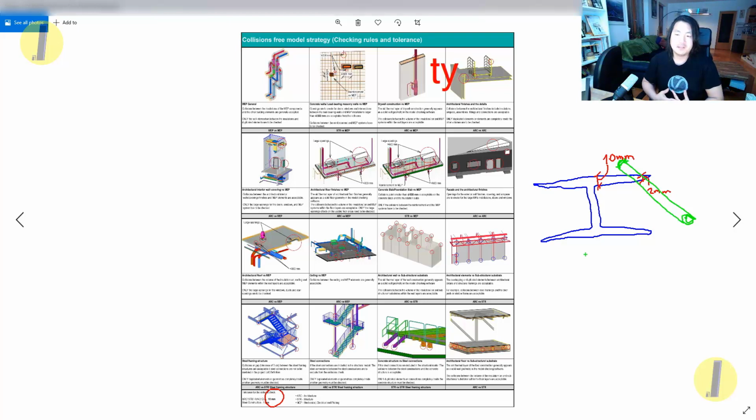and on the planner side, if there's no agreement and you just set 10 millimeter as your tolerance, all these collisions could be completely ignored from your report. And then the control company, the project management company, they set everything to 1 millimeter, and they could report every single collision as a collision and ask the planner's company to take all the responsibility, which is really unfair.